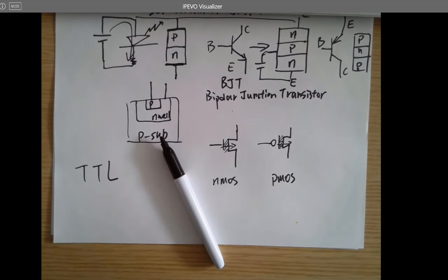So you give data to them in parallel at every clock, and the digital system inside is going to sample that. We don't use parallel anymore. We just use serial communication right now. Why is that? High enough frequency, and parallel takes a lot of pin resources, right?